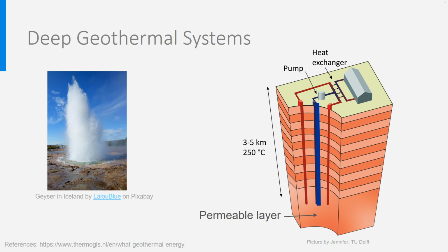The concurrent production of heat and electricity makes such a system much more affordable. Such a geothermal system is relatively expensive as the tariffs are around €1,000 per meter. Boring down to 3 kilometers and using 2 wells would lead to an investment of 6 million. These systems are generally used to heat complete districts or cities and are never used solely at building level.